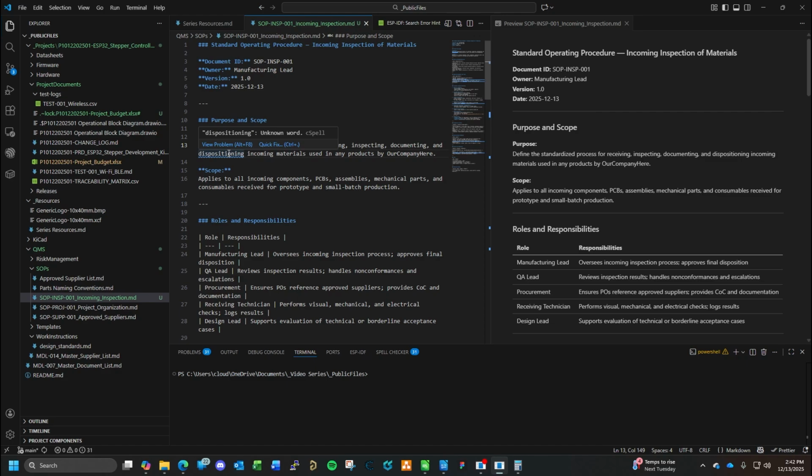It needs to be segregated. You are not to mix bad, faulty products with production materials, even if it means you have to isolate a whole batch, a whole order, while you work on resolving the problem. So it needs to be set aside, and a special process gets kicked off for disposition resolutions. And that's a whole other animal.